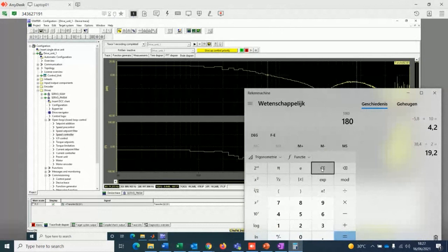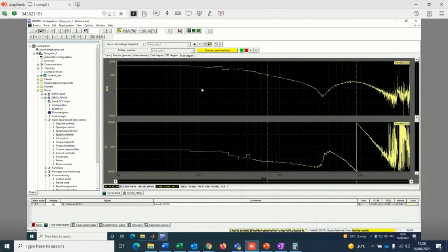So we take 180 and we subtract that value, and we can see that our phase margin is 72.3, which is actually close to the 70 that we wanted to achieve, but it's good enough because it's higher than 70. So the higher, the better the response in this case, because we are more interested in the overshoot, but the system itself is fast enough due to the characteristic of the servo motor. So we want to reduce overshoot, so a higher phase margin will be better. So we need at least 70 and we achieve 72. So the design is okay.